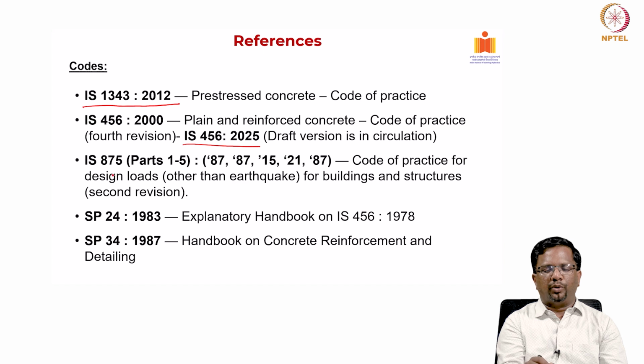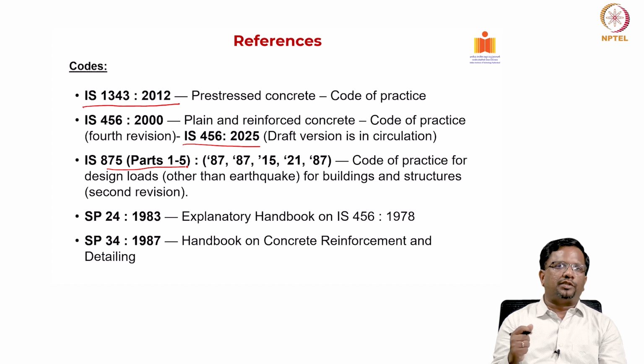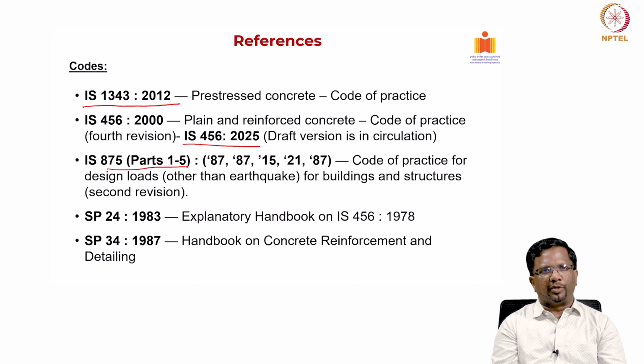With respect to loads, again we will be following IS 875 parts 1 to 5 on how to take the design loads. We will predominantly take from IS 875. And we will also use some special publications like SP24 and SP34.